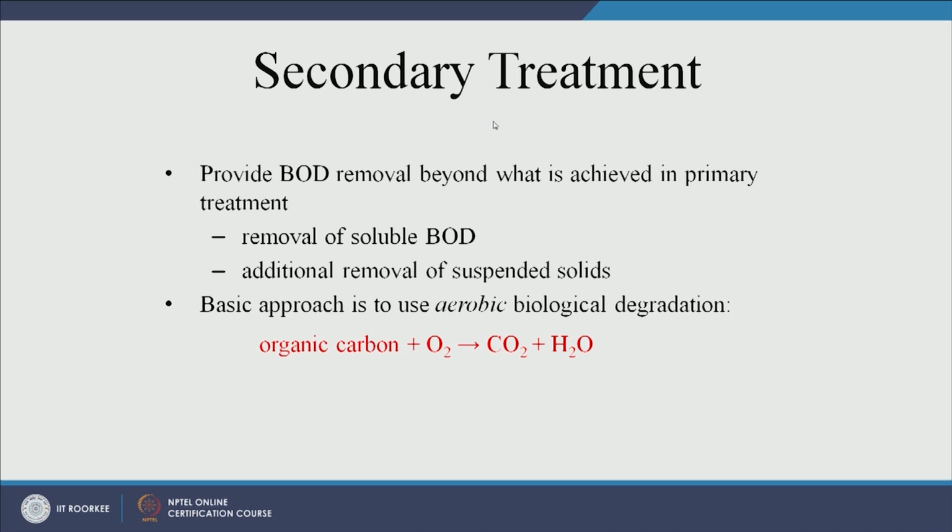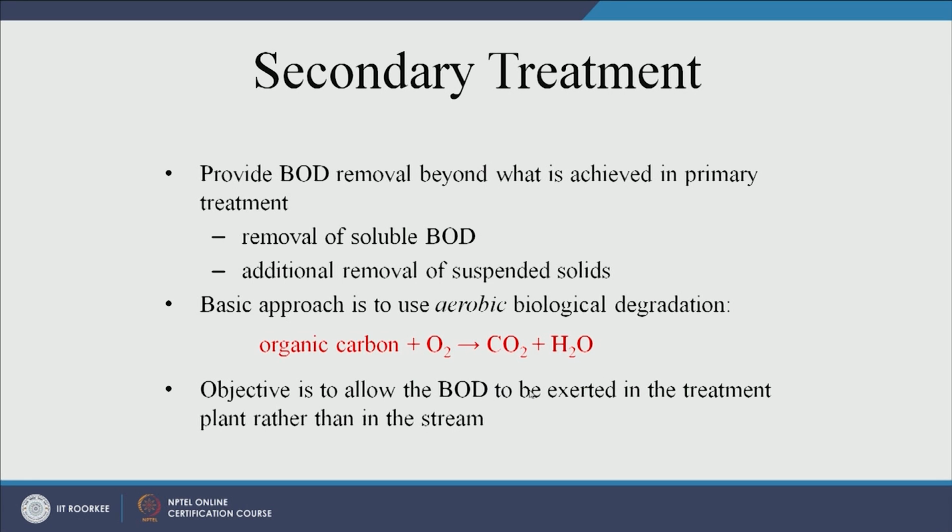The basic approach in secondary treatment, as I have mentioned before, is biological aerobic oxidation. We have a lot of carbon, that waste material, organic carbon, which serves as food, as electron donor and carbon source, and it is aerobically degraded, mineralized. The objective is that whatever oxygen the microbes require to degrade the waste should be made available in the secondary treatment process, so microbes can consume the waste as much as possible in the secondary treatment